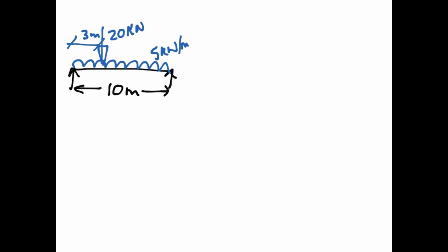Now the reason I've given you these values is on a simply supported bridge with no moment restraint, the maximum bending moment due to UDL is at the middle. The maximum bending moment due to a single point load is at the point of the point load. So where in this scenario will the maximum bending moment occur? This is where we go back to the point of zero shear, which I've mentioned many times, and this is where it really comes to understanding it.